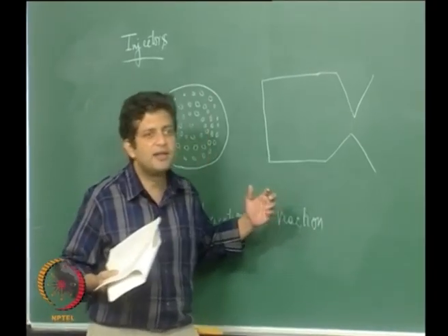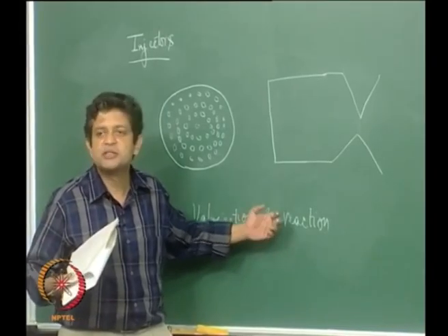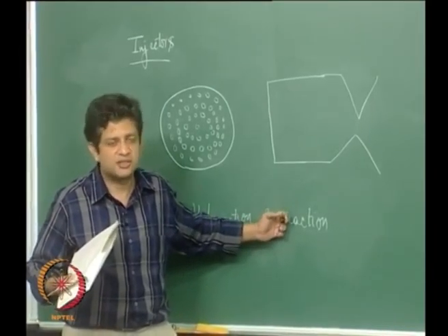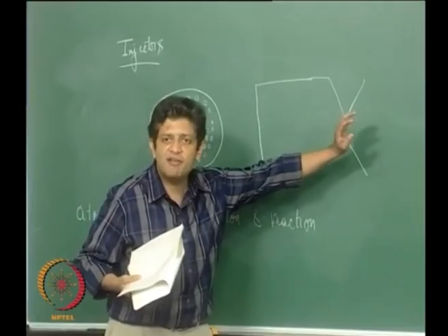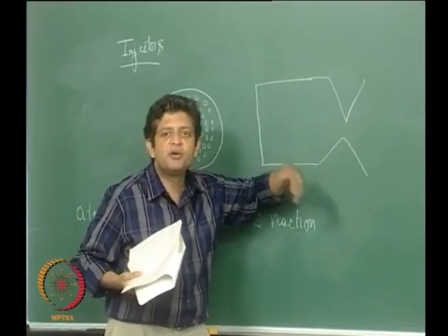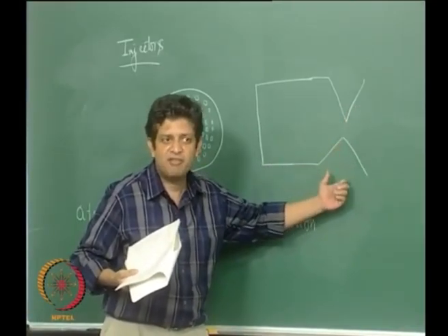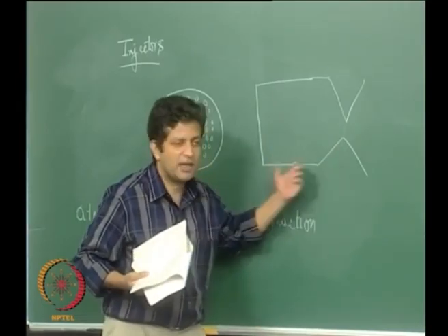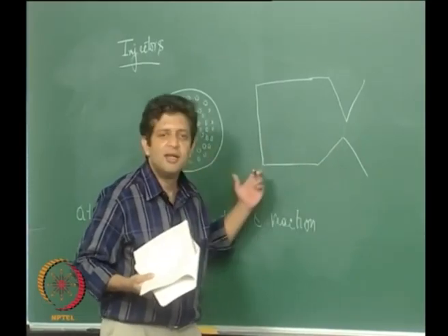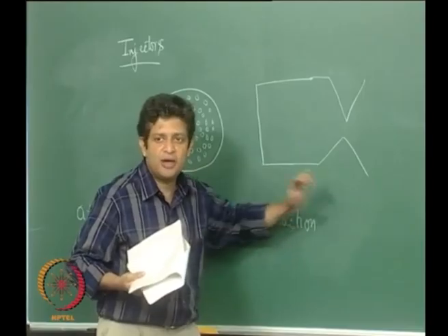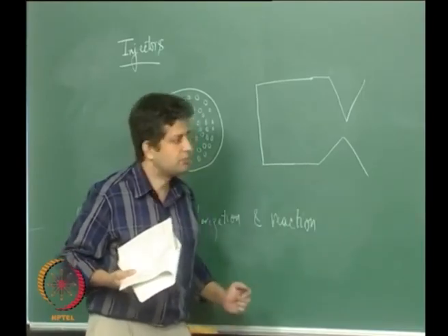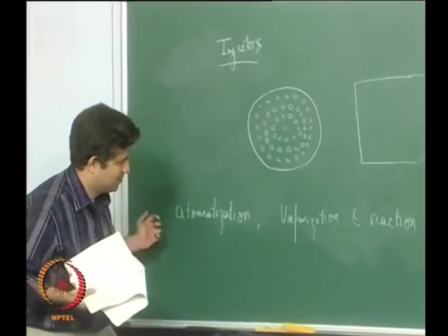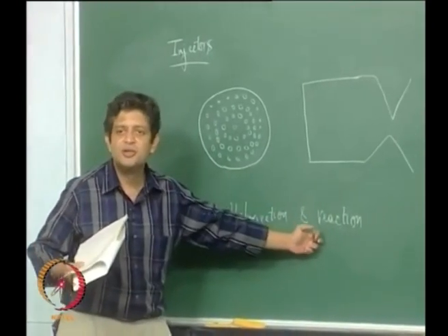The heat release that we get depends on the combustion efficiency. If reactions take place after this, then we will not be able to utilize it that effectively. So you need to have all the reactions or a large fraction of it completed before it enters the nozzle.